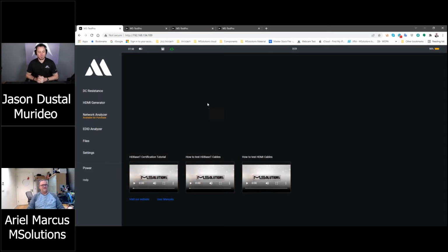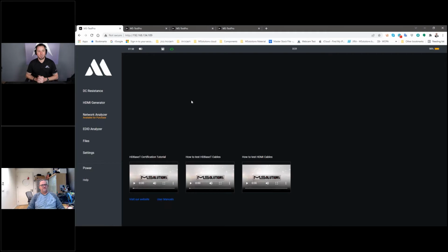I wanted to meet with you today because we have some existing modules for the MSTest Pro, but new features that were added to that. And on this particular video, we want to take a look at the DC resistance module specifically and talk about that, talk about some of the new tests. And once we run the test with your live demo, we'll show the folks the different reports and what to look for. And basically, other than testing the integrity of the cable and the video signal, this is an additional test that will test the health of the power running through the cable.